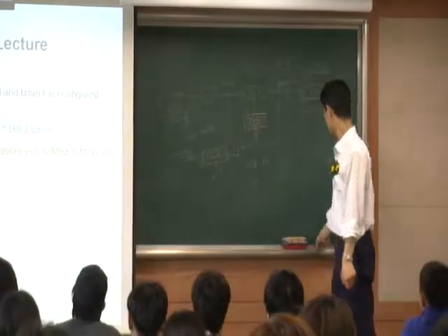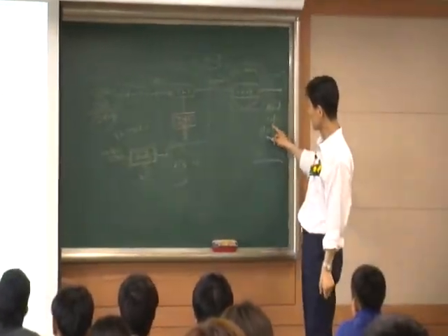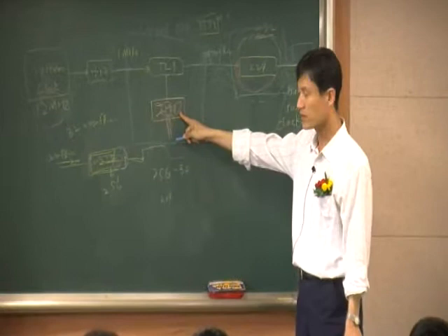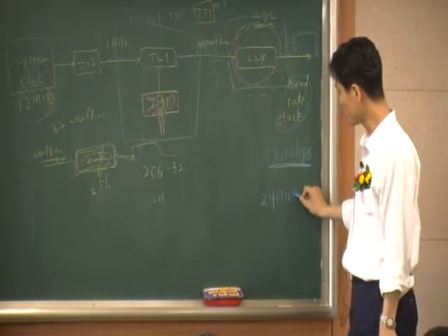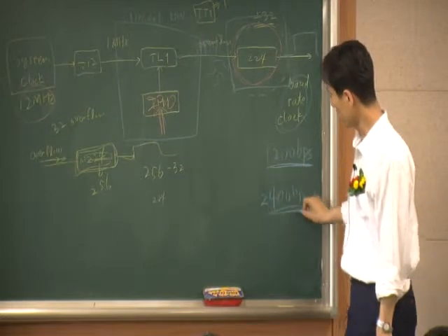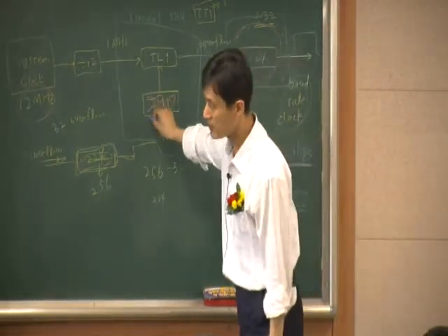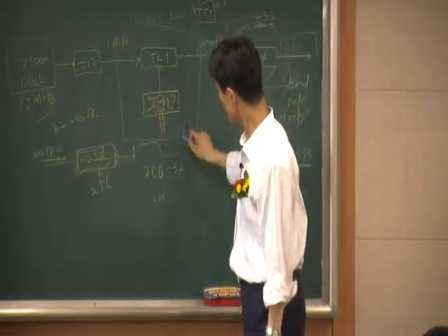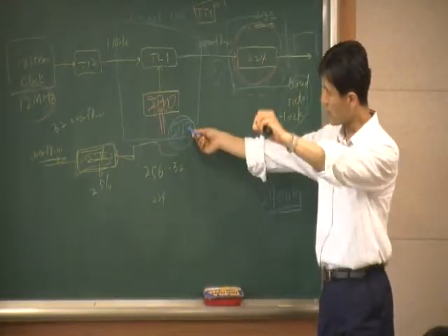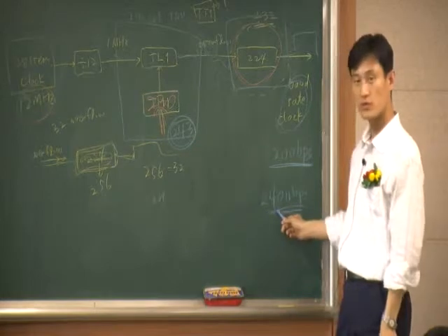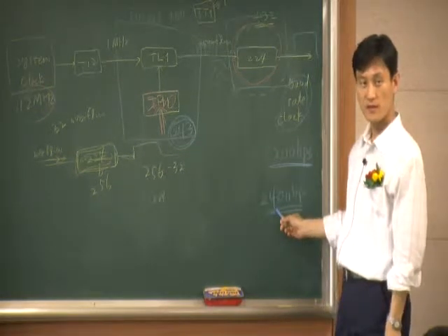In order to get 1200 bps here, I programmed 230. But instead, if I want 2400 bps, then I program the initial value 243. This is the initial value that I want to use to get 2400.